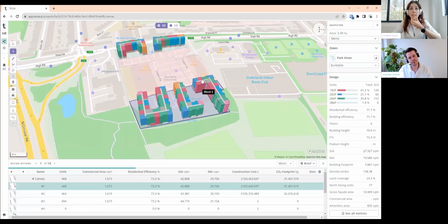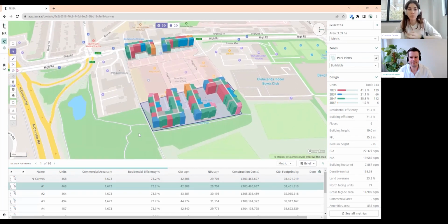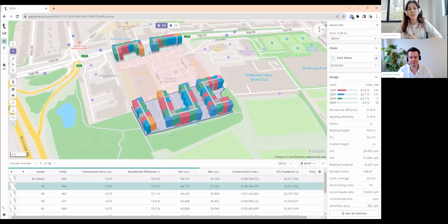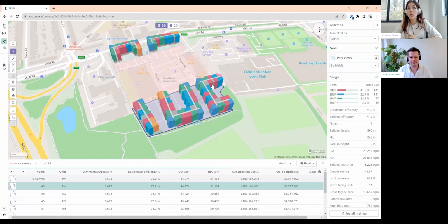And the wing height editor allows me to customize a design option that has already been generated. So I can go in and change the height of the building, but not change the building alignment that I'm seeing here. And that's very applicable for the use case that we're seeing. Again, I'm going to first select the option with the most units, which is this one. And it's also very fitting because it has a lot of wings. What we call wings are, for example, this building has 3 wings. So they're like the different sections of the building.